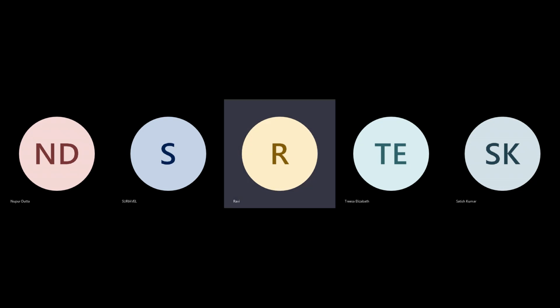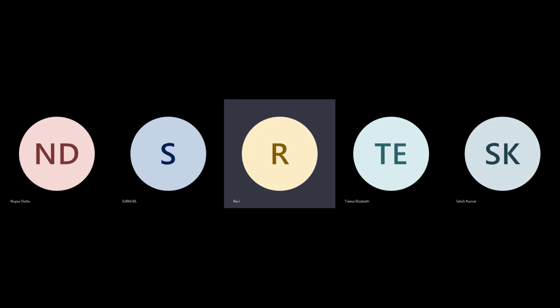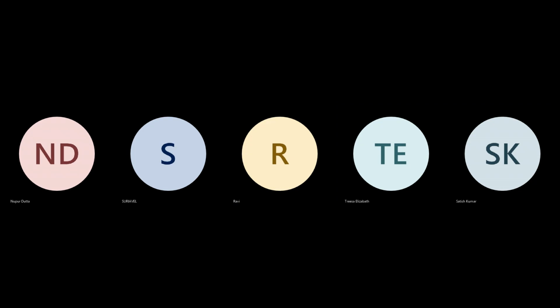You look at how the feedbacks are coming, right? And then see why this problem is essentially happening. Okay, you can do route guide, push this. You may see that this is happening, but it's only happening in M1. This is what you can look at, right? It may be happening, so push that. You have like 5, 6 layers, but this routing is happening in M1 only because of tight timing it's trying to meet. You add like M1 density 60%, push that route to M3, M5, like that.